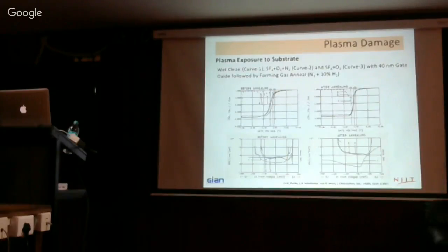Have you tried anything like that? Leakage current changes your CV measurement. It has a lot of impact. The best way is to use a thick dielectric, where your leakage current is low. Then you can check that one. Then you increase the leakage current by stressing it, which creates a lot of defects. Once you stress and defects are more, the leakage current goes up. Then you see the shift again.